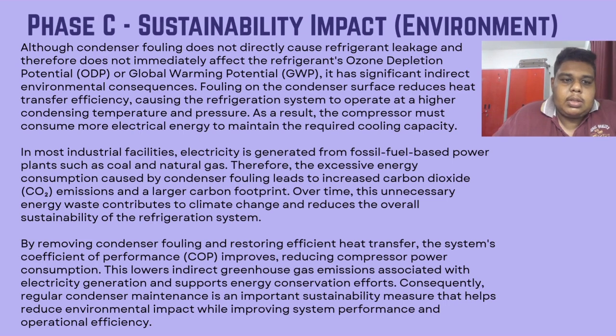Now I would like to present Phase 3, Sustainability and Environmental Impact. Although condenser fouling does not directly cause refrigerant leaks or affect ODP and GWP, it creates significant indirect environmental impact. Fouling reduces heat transfer efficiency, forcing the compressor to consume more electricity to maintain cooling performance.